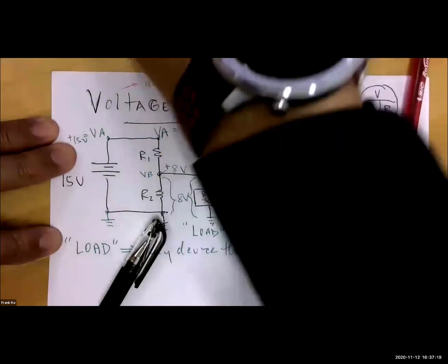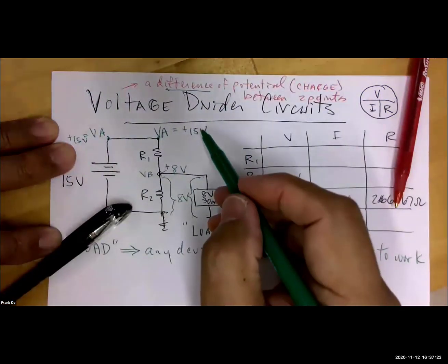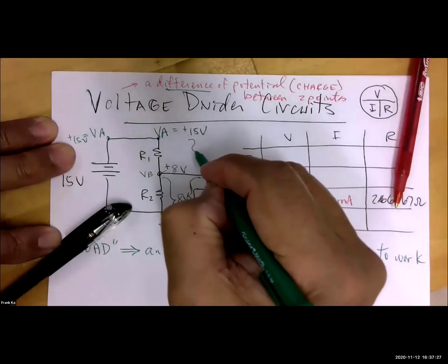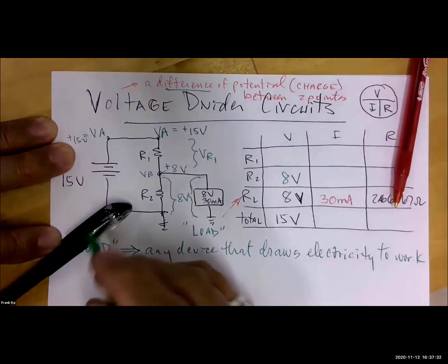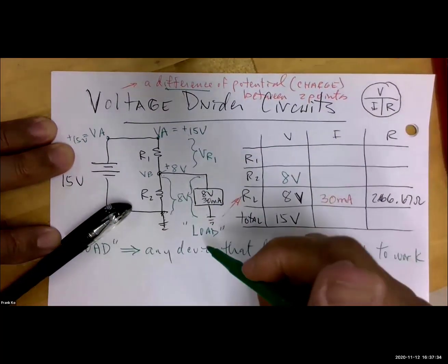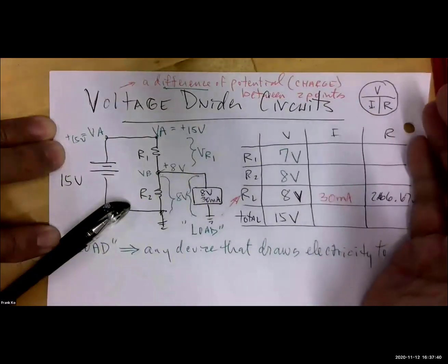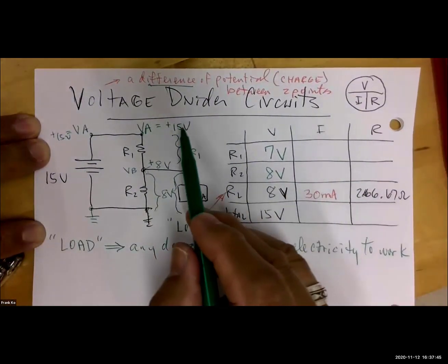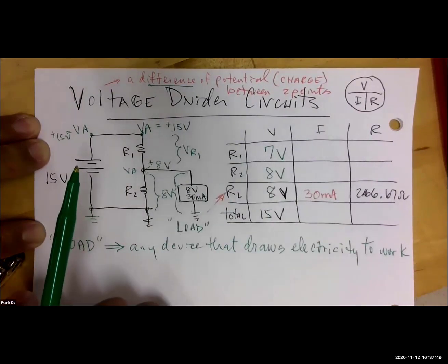So voltage, defined as a difference, means, Jackie is right, we're going to subtract. 15 will subtract the 8. So therefore, how much voltage will be across R1? 15 subtract 8 will give us what, Jackie? 7 volts. So we will write 7 volts right there. I just verbalized for you all a reminder of how we justify calculating 7 volts here. Okay. All right. This is very good.